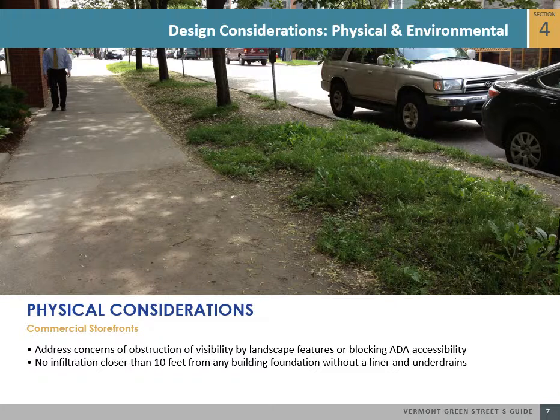Any infrastructure placed within 10 feet of a building foundation should not promote water migration underground. Lined filtration practices with underdrains or container landscaping will capture rainwater without diverting it toward building foundations and can safely and effectively be employed in space-constrained downtown locations.